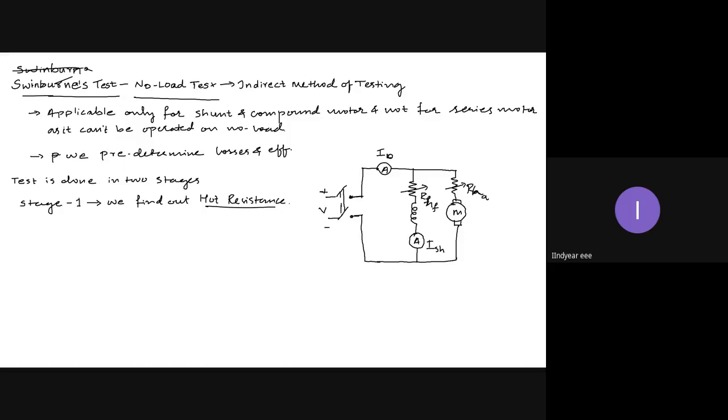Sometimes it is more than 50% also. An induction motor draws more than 50% no load current when compared to the line current. If the line current value is 10 amperes, the no load current drawn by the induction motor is around 6 to 6.5 or 7 amperes. You cannot say, seeing that, that the motor is at 70% load condition.